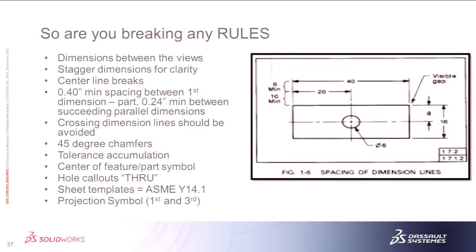But a lot of times we don't see that little plus sign, and that's kind of a little pet peeve of ours. Most of that time is because when you're dimensioning and you have center marks in there, you've got to click on the center mark, not the hole, to get that to work right. SolidWorks has done a good job of improving that over the years. Used to, you pretty much had to put your center marks in and dimension to them to get the break. Nowadays, if you dimension to your hole and add center marks, it does a pretty good job of being smart enough to realize what you're doing and give you that break.